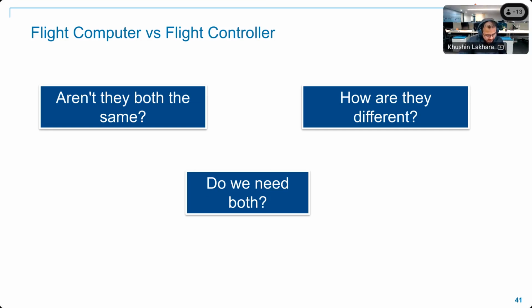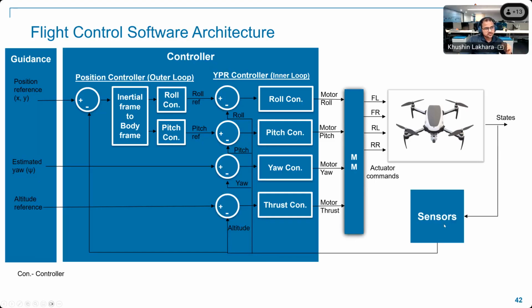The controller takes care of stability, and your flight controller hardware comes with multiple sensors, like your IMU sensor, accelerometer sensors, and magnetometer sensor, and they help you stabilize your vehicle motion. But when you want to perform high autonomy missions or smarter missions like obstacle avoidance, or follow a particular object in the environment, in all such cases you need the flight computer, which has the particular perception algorithm for that. For all these purposes, we go for the flight computer. So yes, they are different.